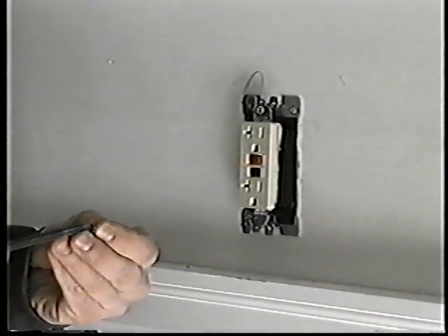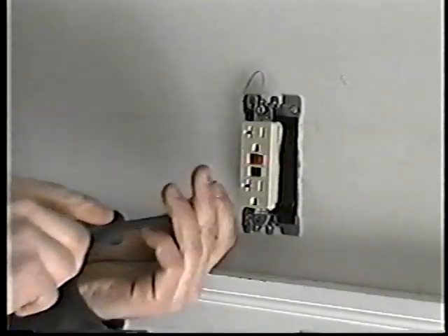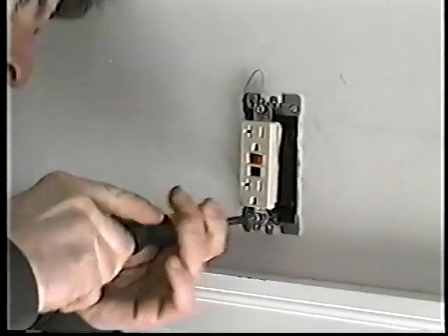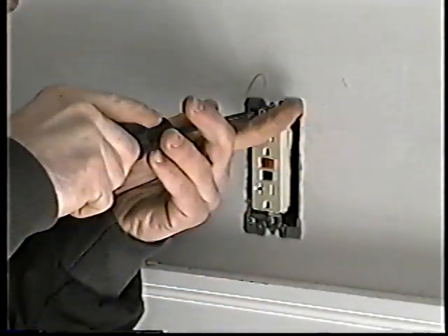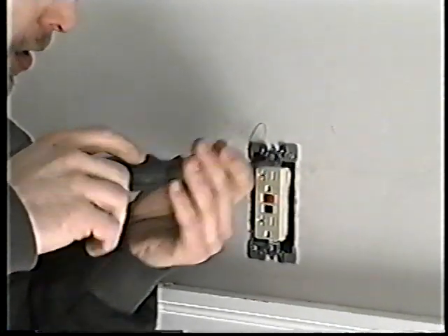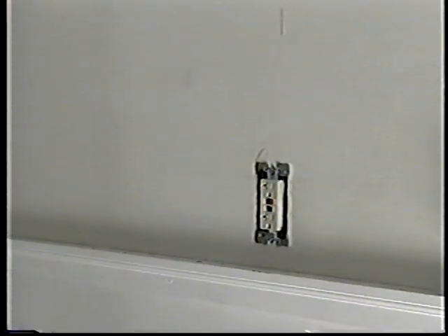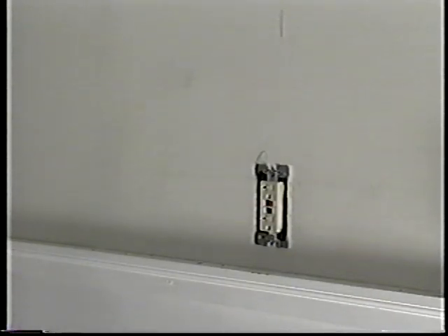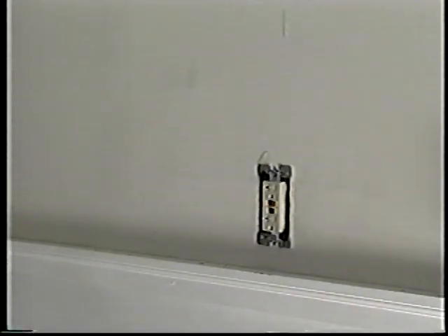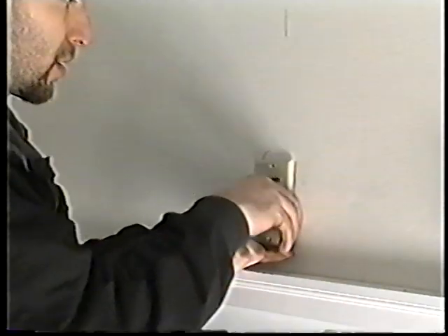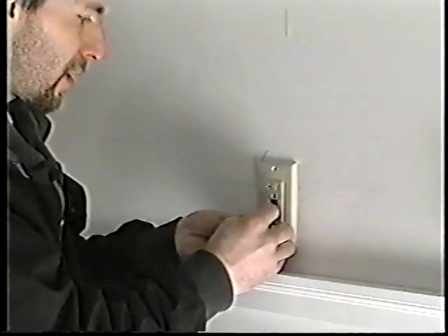With these boxes I use, these ones are nice. You actually can just push the screw in, and then when you're done, you give it a final twist, and it just snugs them down. It's a lot less effort. You don't have to do all the turning with the screwdriver. And then the final step is every outlet and every switch should have a cover put on it.